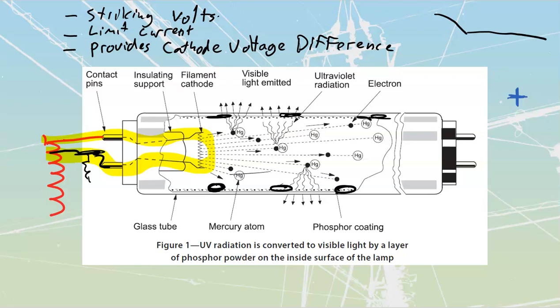We talked about this in transformers: you cannot allow it to get too warm because the insulation gets too weak and we lose those oily parts, the volatile organic compounds, and we start to have problems. The ballast should last 12 to 15 years is what the book says. It's not uncommon though to see ballasts out there with a 20+ year operating life.